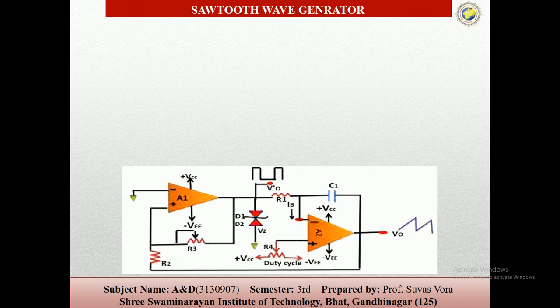Depending on the R4 setting, a DC level is added to the output of the inverter B. So here we can change the duty cycle, whichever type of duty cycle we need. So the output voltage of the inverter decides the effective voltage at the point P, adding a DC level to the output of the inverter.